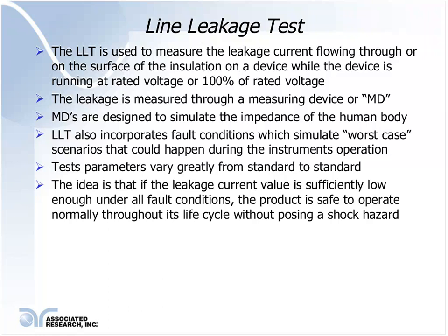Again, the idea behind running tests under these various configurations is to measure exactly how much leakage current a human could be exposed to while the product is running and subjected to a series of fault scenarios. If the leakage current value is sufficiently low under all such fault conditions, the product should be fine, or should be able to operate normally throughout its life cycle without really posing a shock hazard.